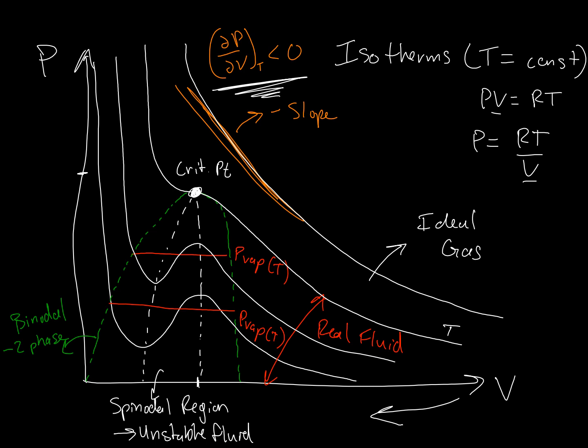As chemical engineers, we're not necessarily as concerned with more accurately predicting the density of the gas as a vapor or a liquid, which is very important for some fields. I'm sure in reservoir engineering it's really important to have an accurate equation of state because you want to know what the PV relationships are down the well. But in terms of a chemical plant or a refinery perspective, we mostly care about using equations of state to calculate phase equilibrium and calculating the Gibbs free energy. So in that sense, the cubic equation of state is extremely powerful because it has this region of instability here.